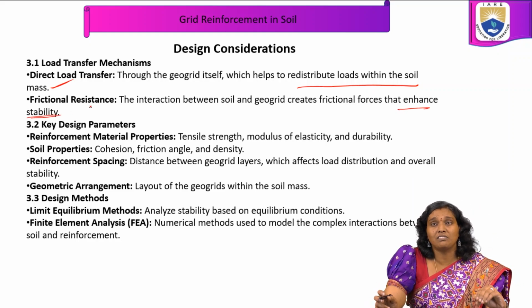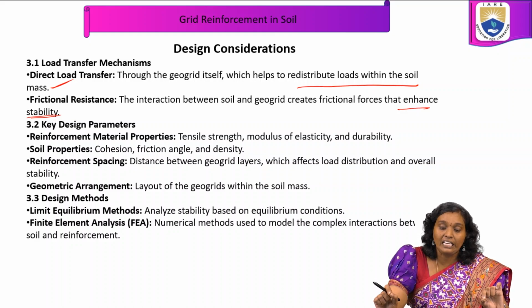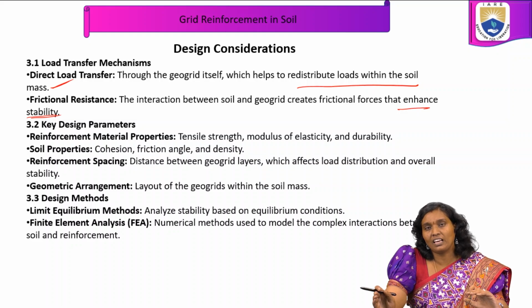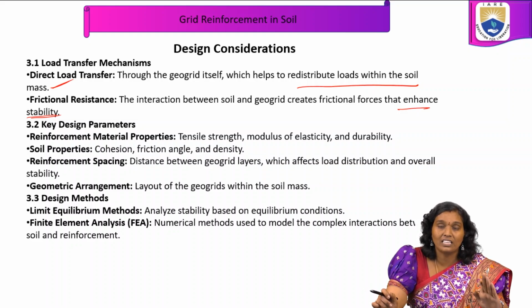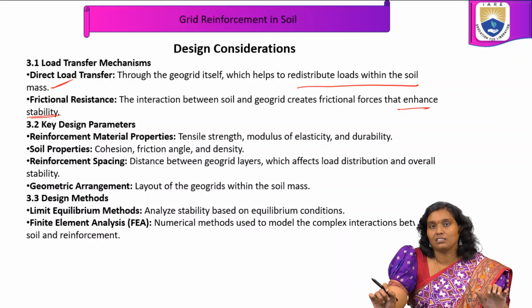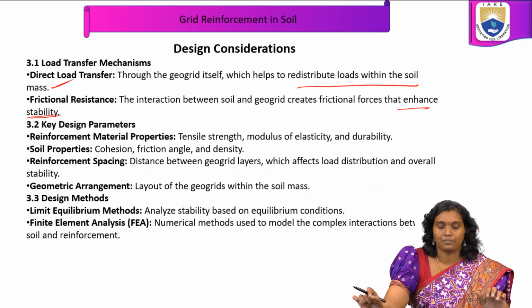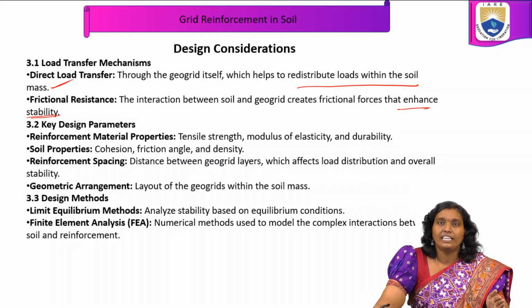The load transfer mechanism is one of the major parameters in grid reinforced soil as per design consideration, so we have to understand it based on the soil conditions and the required properties of the soil for the type of construction work. The design parameters are reinforcement material properties, soil properties, reinforcement spacing, and geometric arrangement.